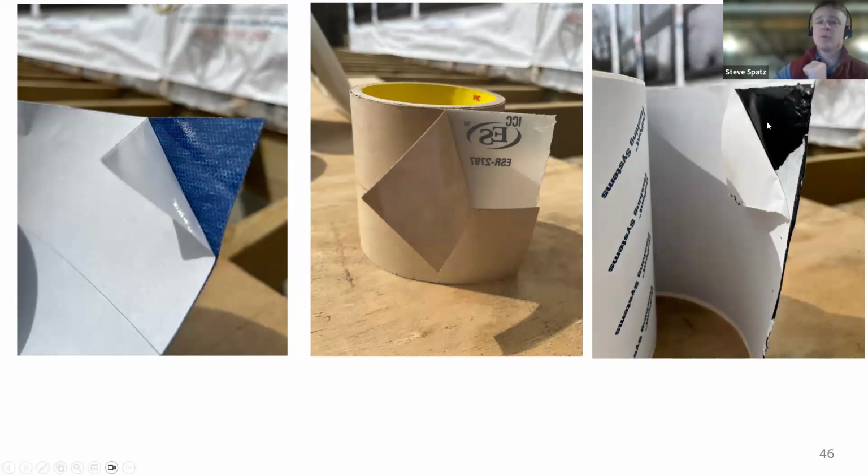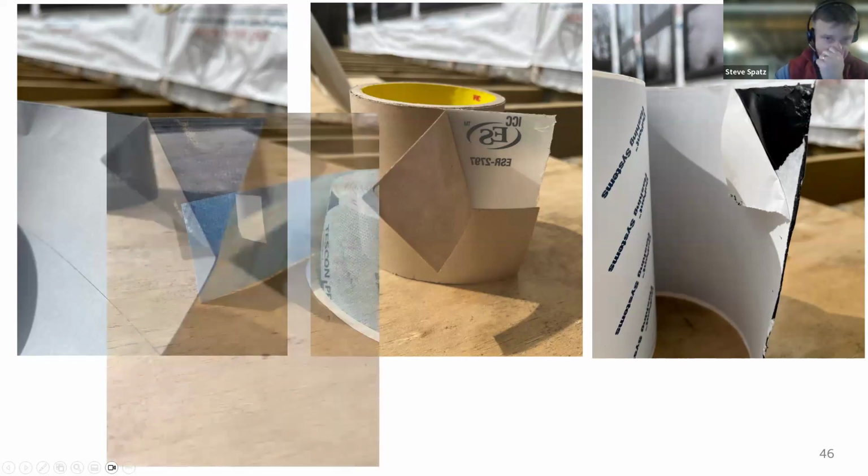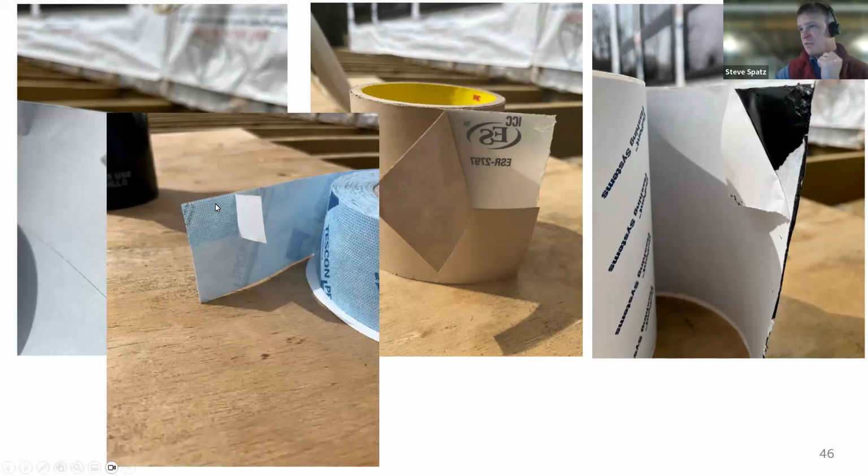These are now getting into butyl tapes where you're looking at specific applications for shedding of water around window and door rough openings, and potentially why you'd choose this type of adhesive over any of these other three. And then you get even into more detail about specific tapes that are engineered for specific purposes. These are some of the other vapor permeable tapes that are designed around window installations and sealing around specific joints where you need a bend in the tape to make that transition occur well. And then adhesive gaskets that would bridge that gap. I think, Evan, to what you were just saying, between your sheathing and your foundation. Somewhere if you overhung your exterior sheathing past the sill plate down to the foundation, which is pretty common, you could use a gasket like this as a point to seal that gap or tape.